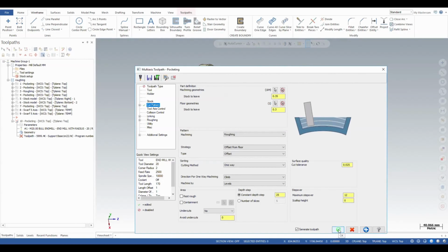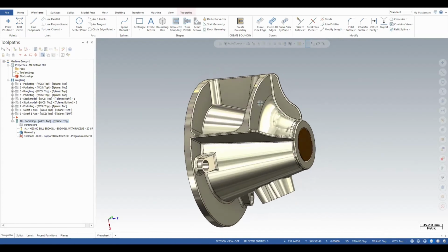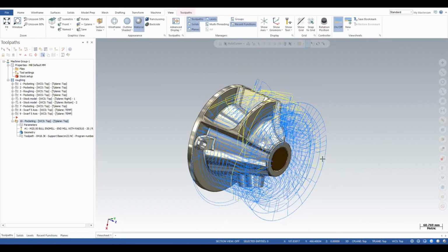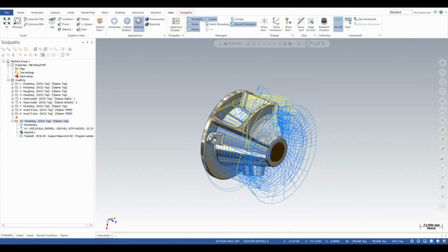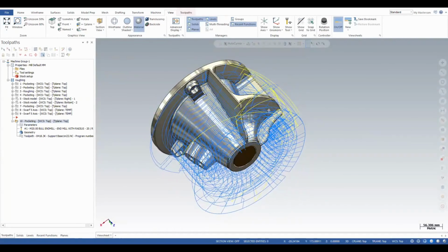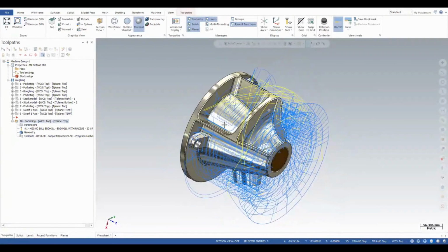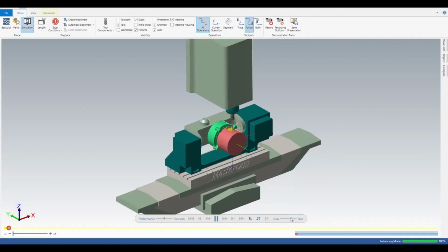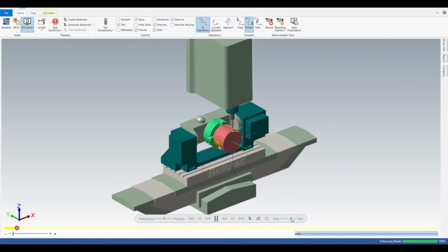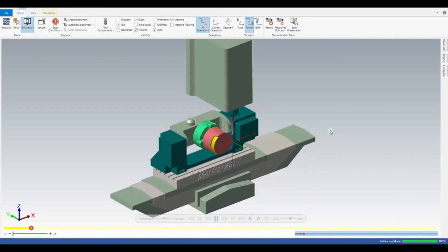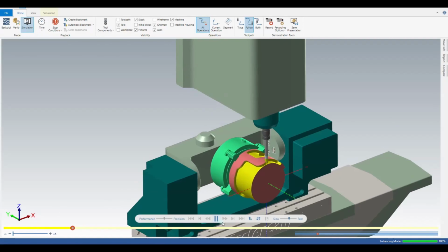Stock setup is nothing, and go to the settings of the first operation. I'm going to change the floor, reselect the floor. Previously the blue color surface was generated. Select the surface. Now the tool axis control surface, the center of the cylinder, will be selected, then let's see the result. Nothing else to change, only the center of the surface changes, and the toolpath is generated.